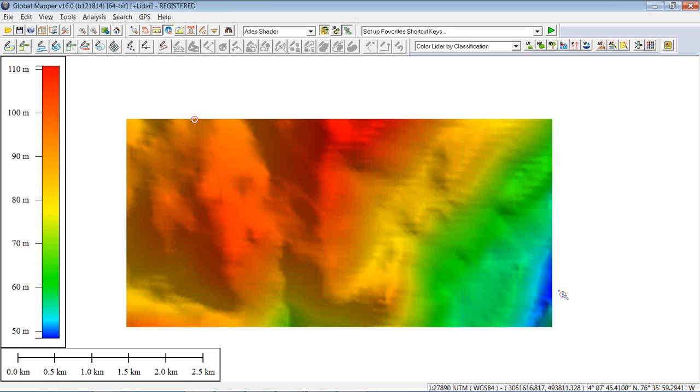You could quite literally walk around an area with a GPS receiver collecting waypoints. If your GPS receiver includes the ability to collect terrain as well, the array of points that you create could essentially be used to generate a surface model such as you see here. Obviously the accuracy of the Z value will be dependent on the accuracy of your GPS receiver. The example that Josie showed us was a fairly regular array of points, but it doesn't have to be. It can be a randomly arrayed point layer that can be used to generate this surface. So, excellent.